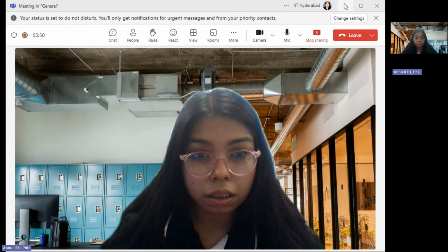Okay, so I'm giving you the step-by-step solution. First, the time shifting property leads to this. The ROC, if you talk: x of n is causal. Shifting it right by n naught greater than 0 still yields a causal sequence. That is, the ROC remains mod of z greater than r. If shifting by n naught less than 0, remember, it may change the causality, so carefully recheck the boundary. So the conclusion is the transform is z power minus n naught times X of z, with the same ROC except possibly adjusted for boundary shifts if the sequence becomes anti-causal.